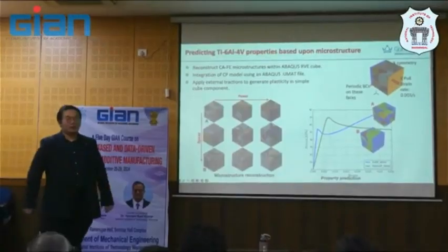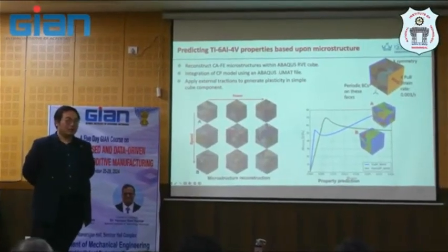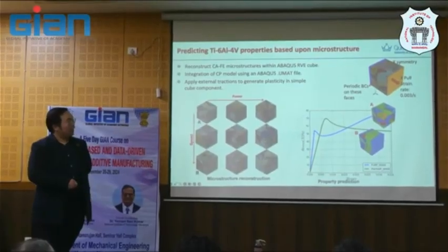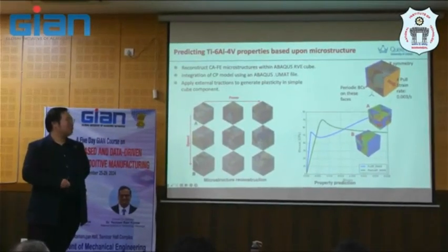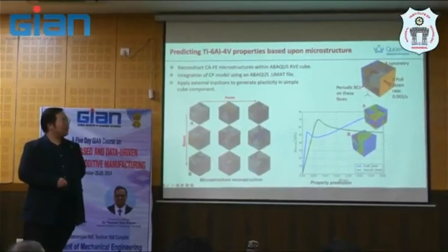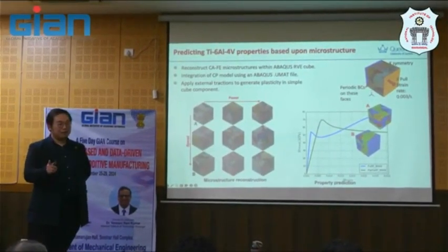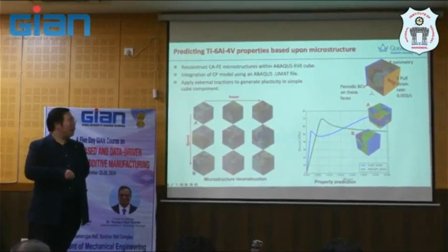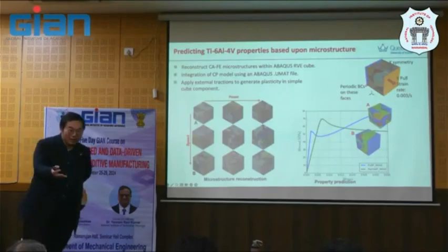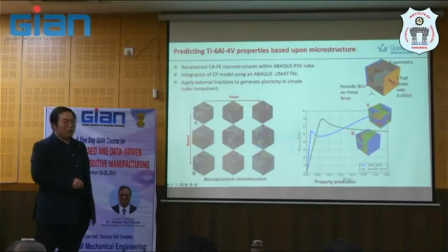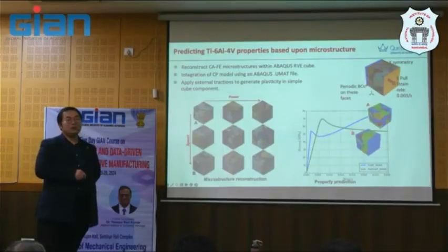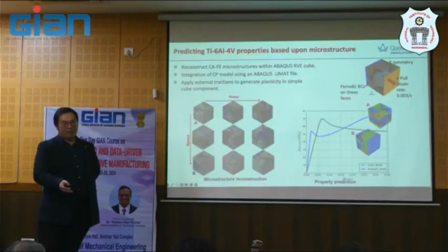Again, this one is, I would say, a representative result that we show you. It's probably a bit of an overestimate, because we assume that we simulate the beta phase. Is that okay? Beta is BCC. And then if you change from equiaxed to columnar, based on the constitutive law we have, it behaves like this. Again, this is just the simplest plasticity model we apply. Detailed calculation is needed. This is a proof of concept framework that we propose.